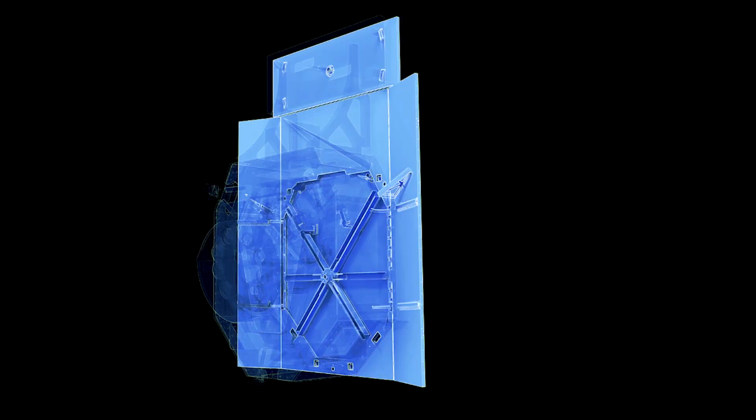The WFI thermal system keeps the instrument subsystems at their ideal operating temperature. A system of metal straps and heat-conducting pipes will carry heat produced by the detectors and electronics to radiator panels that face cold space on the outside of the instrument. The excess heat will be radiated away, cooling the instrument components. Thermostats and heaters will be precisely monitored and control the subsystem temperatures, holding them in a narrow and stable range so that the observations won't be impacted by swings in temperature that introduce uncertainty in the precision scientific measurements.